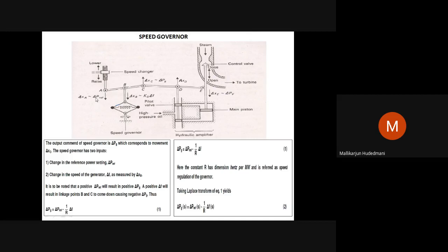No more is there a change of delta P. The governor is going to reflect the drop in RPM or frequency with its droop of R%, such that the shift will be brought to the hydraulic amplifier and the valve opens, so that higher fuel will rush in. That higher fuel will address the drop in RPM, which will bring the frequency error back to zero.